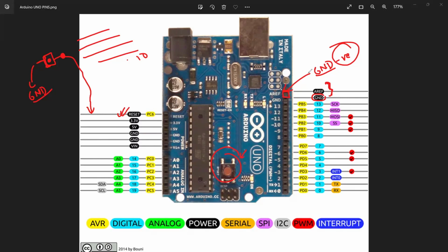One question. So this AREF voltage that we provide, that is the analog reference voltage for the comparator and conversion from analog to digital, right? Yeah, correct. Suppose the default analog reference voltage is 5 volts, right, sir? And then let's say we connect some other voltage, let's assume 2 volts, into that AREF pin, but we forget to declare in the code that analog reference to our particular voltage, and instead just write analog reference in brackets default, then what will be used as a reference voltage in the comparator?